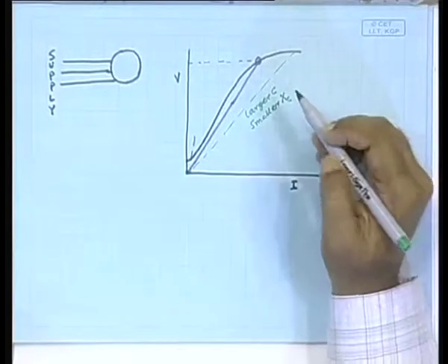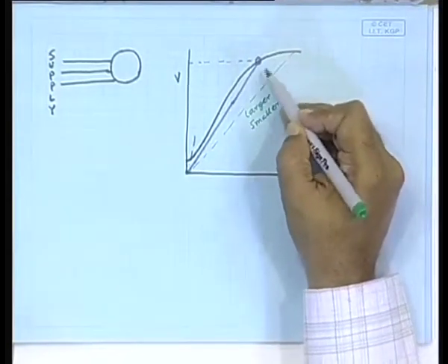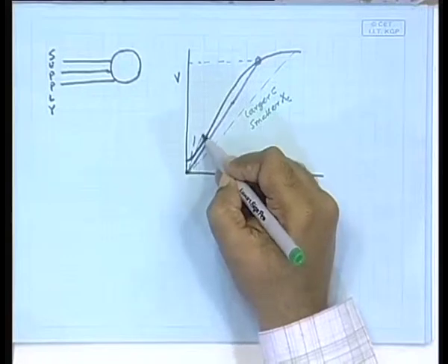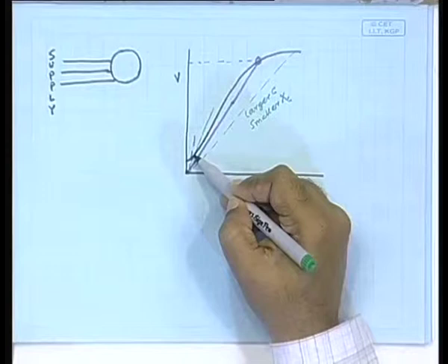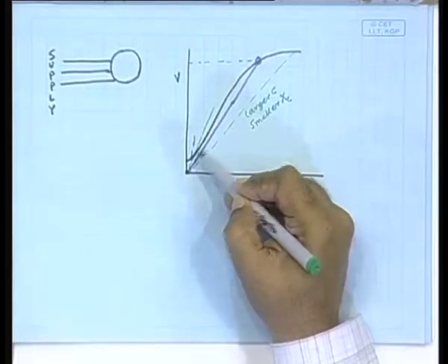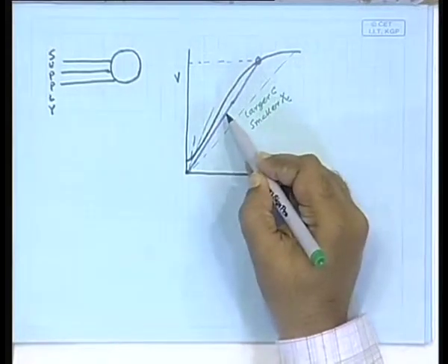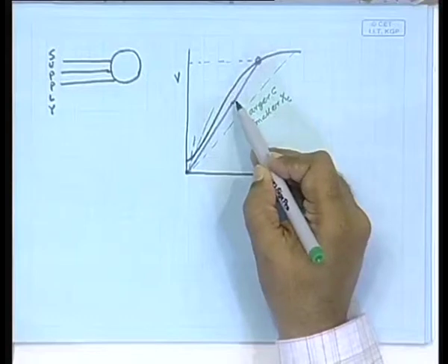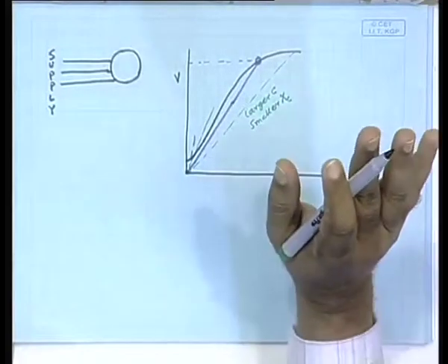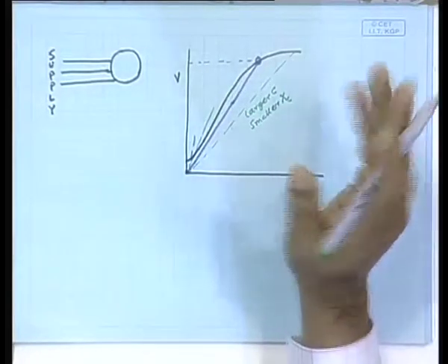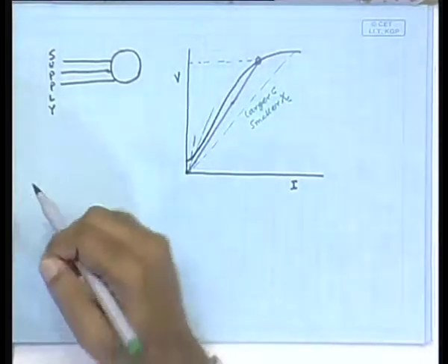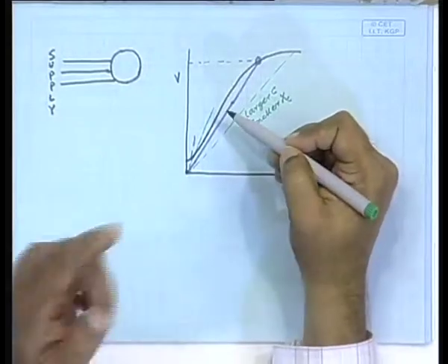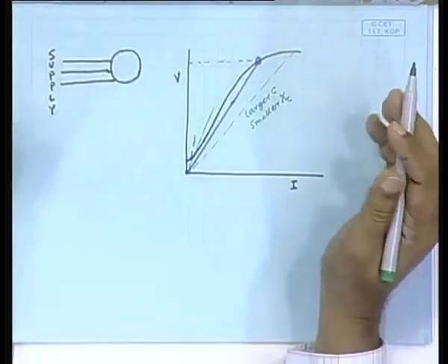Okay. And for a smaller value of capacitance, you can see that again it will not self excite beyond a very small voltage. So, the capacitance value has to be beyond a certain value, that is one point, and for every capacitance value there will be a critical speed beyond which it will self excite. Is that clear?